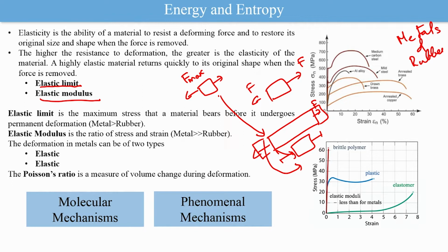So, this is what actually is meant by the elastic limit, and through different material characterization steps, we have found this elastic limit for several materials. And as you might already know, okay, the elastic limits of metal is significantly higher than that of materials like rubber and other polymers, most polymers, okay. Now, the next parameter, okay, so elastic limit is basically nothing but the maximum stress that you can apply, so that the material does not get permanently damaged, you can say it like that.